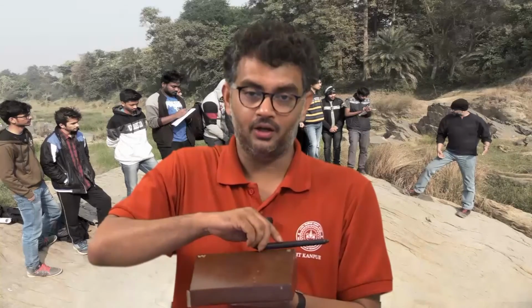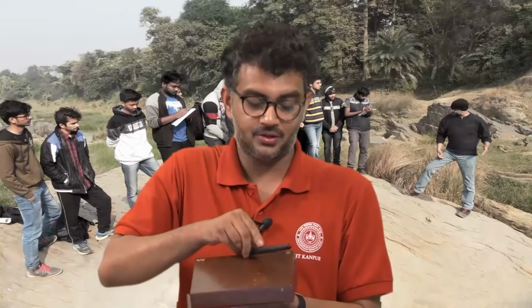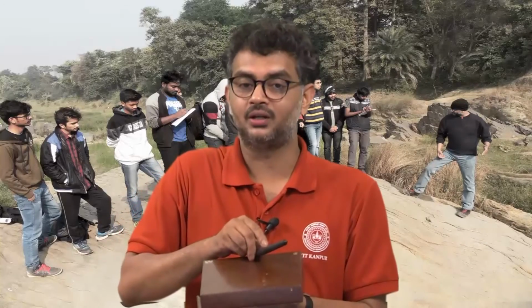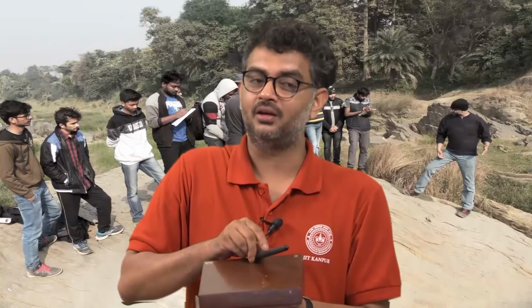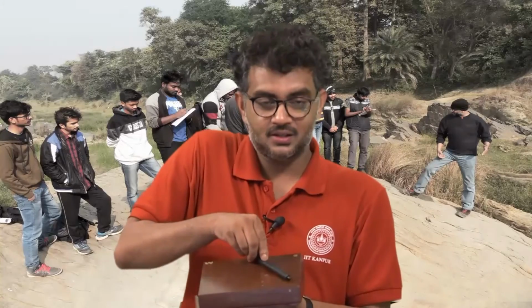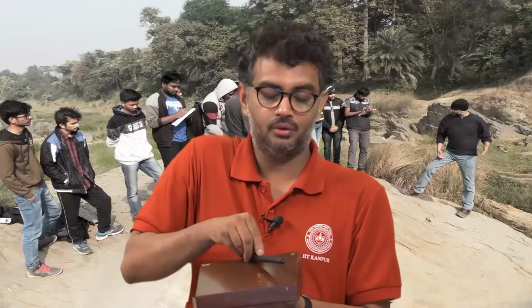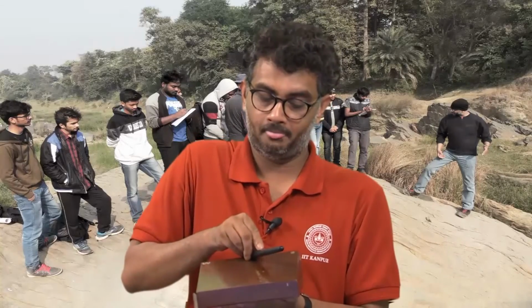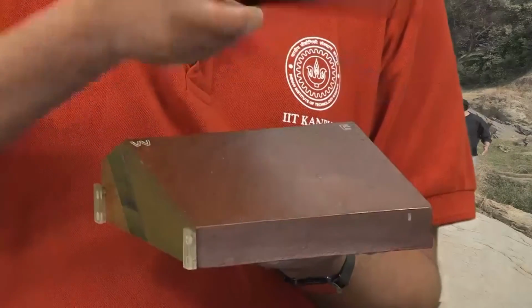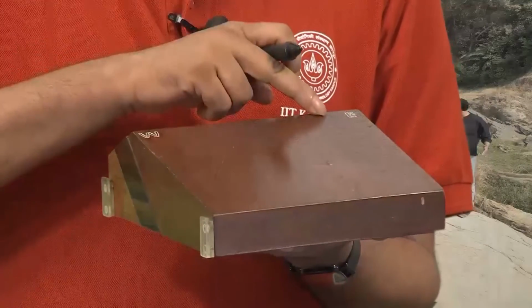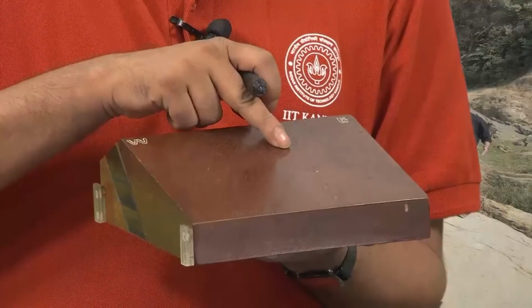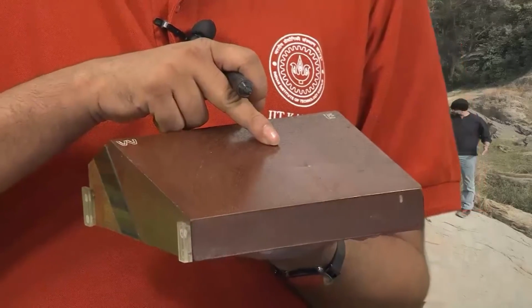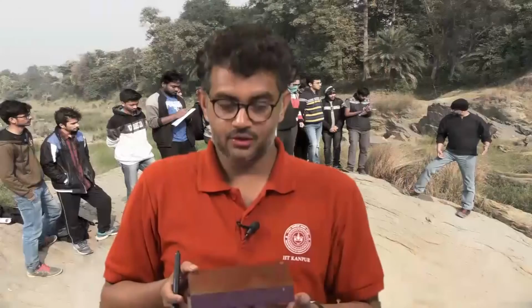Now, if this is my north, then the angle it makes along the horizontal plane is my trend. The plunge is the angle I have to rotate this line to project it on the horizontal plane, and the pitch is, if this is the line, the angle I measure on the plane, also called rake. So, if I try to define it in words, it goes like this.